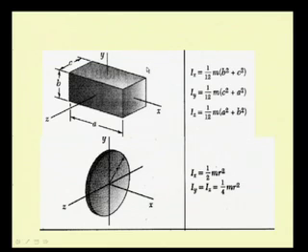So, you can try to quickly remember that these dimensions, that is b and c, are nothing but the dimensions in the plane yz. And the same way, when we compute this Iy, or the second moment with respect to y, we have to take the dimensions in the plane zx. So, we have c and a. So, we have this 1 by 12 m (c square plus a square), and same way Iz.